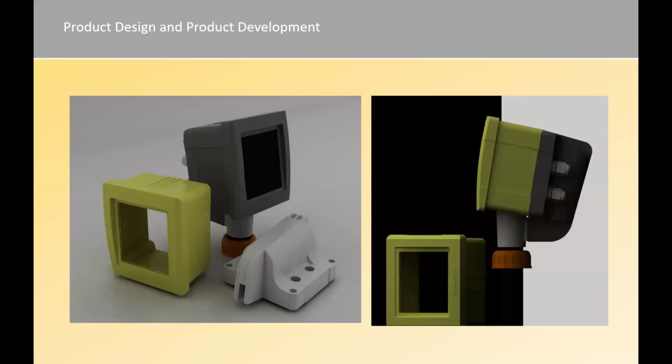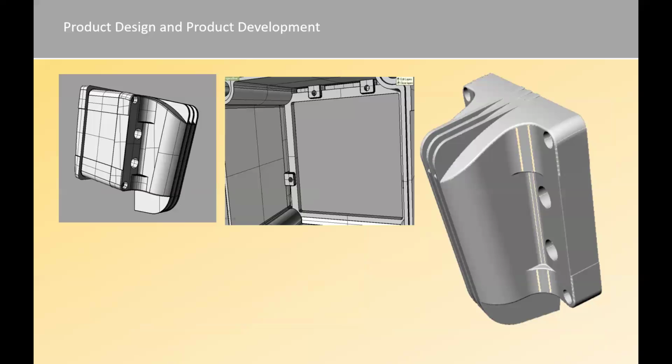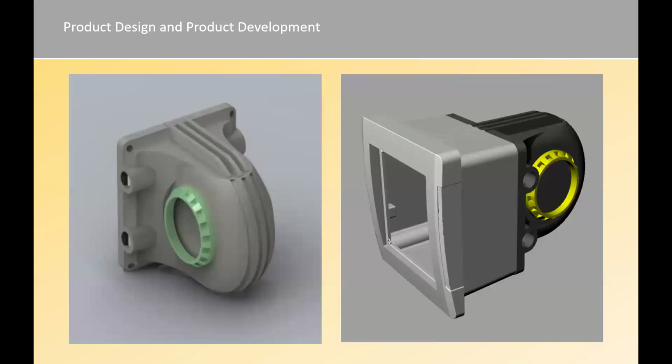Yeah. So there was a minor angle which was also considered for user friendliness. And there is a shade shown over here, a minor shade, because this is a changeable kind of plate. And this mounting over here, you see, is a field mounting. Yeah, it is mounted on the pipe. There is a paddle sensor in the pipe. This is a digital model. This was made for injection molding, ABS plus PC. So ABS plus PC was the material which was used. This was an inline kind of.